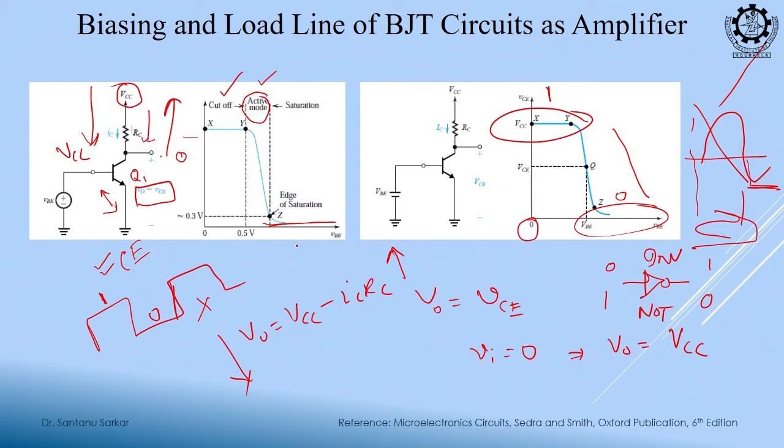Now, here input is very high, right, input is close to VCC. So, base emitter is forward bias or reverse bias? Forward bias. This voltage goes to this collector base emitter forward. What is happening here? Saturation. What is the condition? Base emitter forward and collector base also forward. I will just check it.